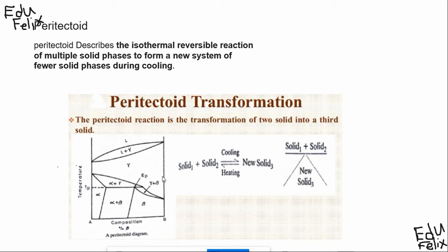Right? So I think now you can grab something about what is behind our phase systems, phase diagrams. So this is a phase diagram. Here you can see this is the gamma phase, this is the alpha phase, this is the beta phase. So there are different arrangements as the composition changes from A to B. Only two phases. There are ternary diagrams also. Ternary means we have a third element also.